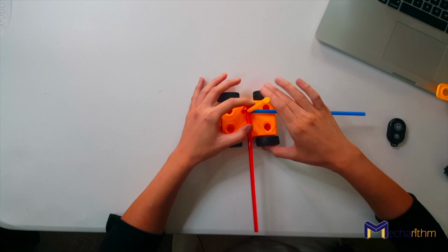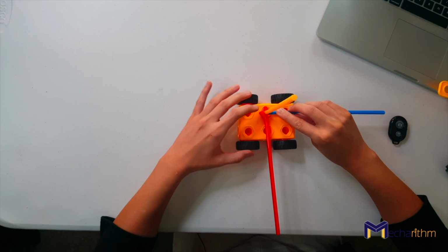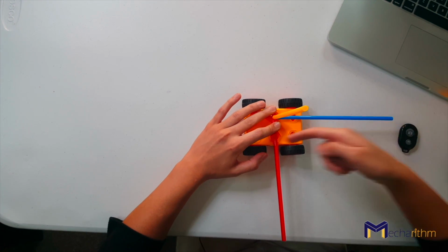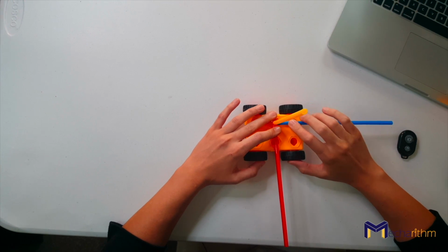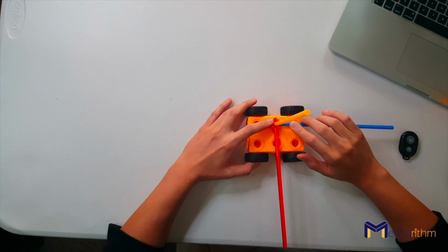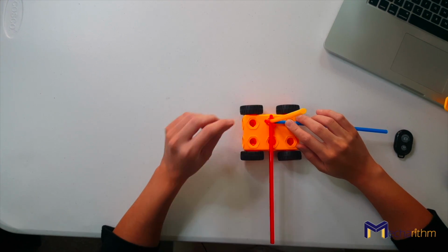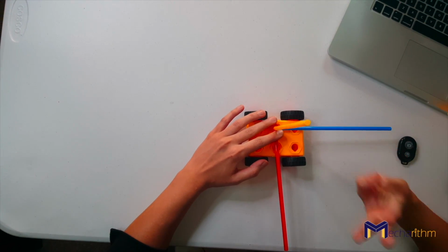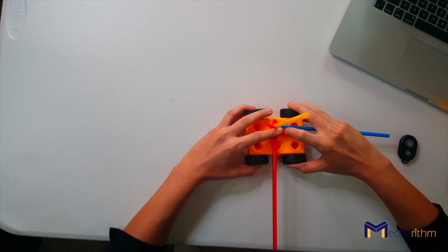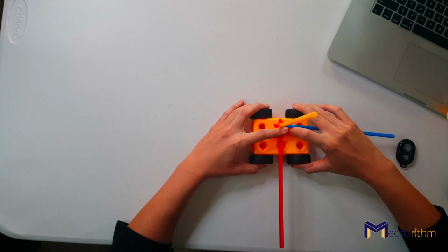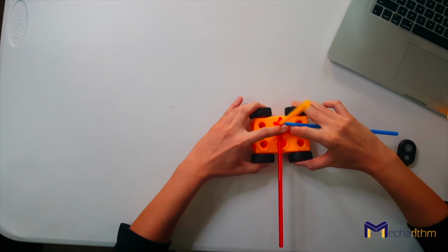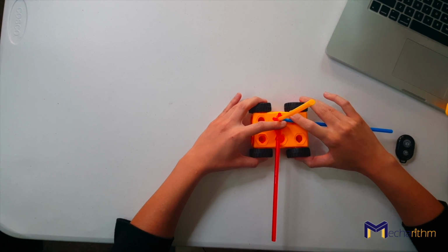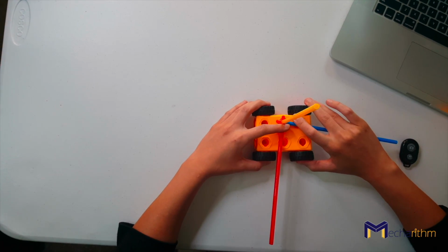Suppose we have this rigid body on a plane, this toy car in the plane, with X-axis and Y-axis. Okay? X-axis, Y-axis, and Z-axis. As we saw, a rigid body in 3D space has 6 degrees of freedom. So if we confine a rigid body to this plane, we will impose 3 constraints on it. It cannot move in Z direction because it's confined on the plane, and it cannot rotate around the X or Y axes. And this means that there will be no roll and pitch angles. So we will have 3 degrees of freedom.